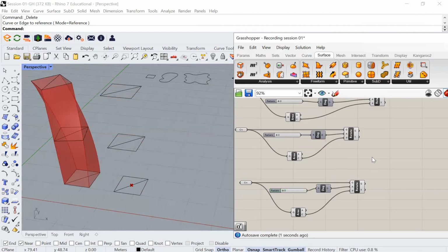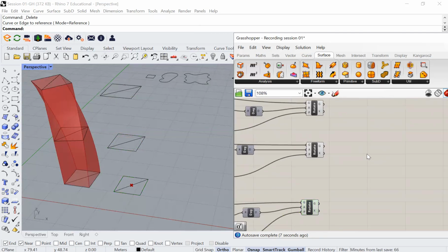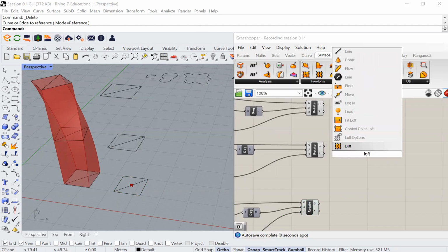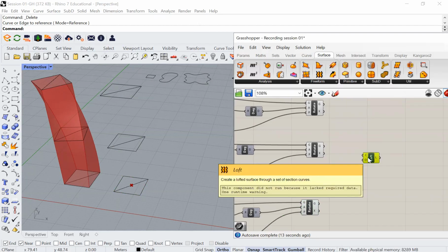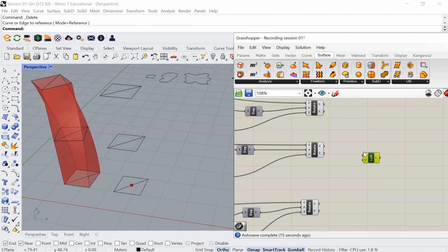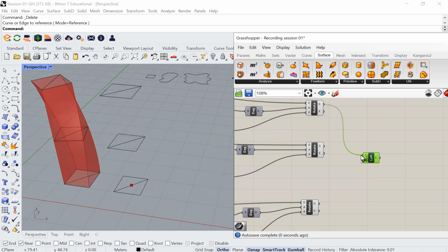And then let's put the loft. So the degree component was added because they looked a bit off for me. Now, when you wanna connect here the curve with the geometry, remember to press Shift while clicking. Okay, I can see how it's building up nicely.